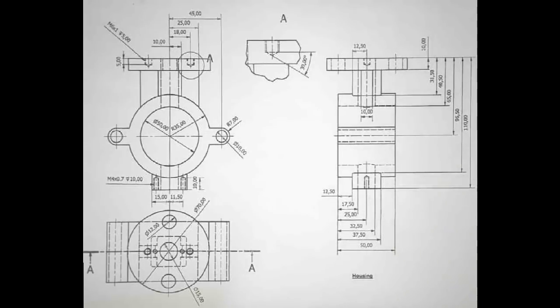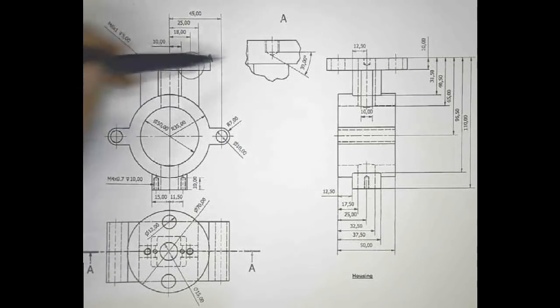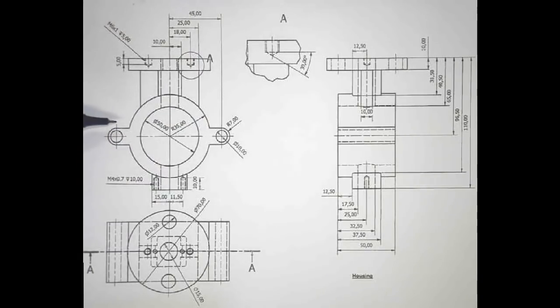Okay, so there are 2 pages of orthographic drawings. On the first page we have only our housing represented. We can see a front, a side, and a top view. The important one for us now is the front view, because that's the one we'll have to draw. And we can also note that section line AA is taken over here on your top view, and that's the section line that will need to be brought through to the assembly.